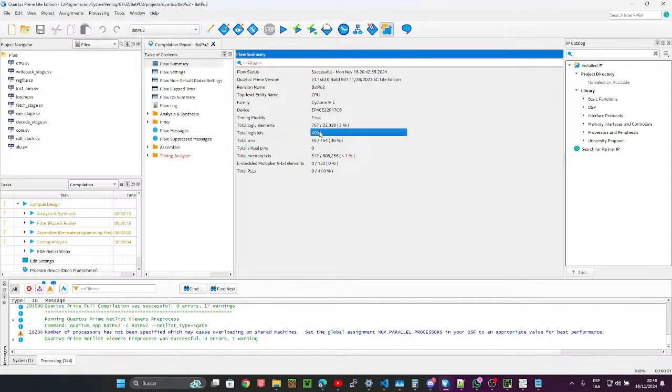Because the DE0 Nano has the Cyclone IV E FPGA, the EP4CE22F17C6. Yes, that's the FPGA on the DE0 Nano. The DE0 Nano has a 50 MHz clock on it. Like, the FPGA has access to a 50 MHz reference oscillator. You don't use that directly, you go through a PLL and you tell the PLL what frequency to output, and you have quite a bit of range.